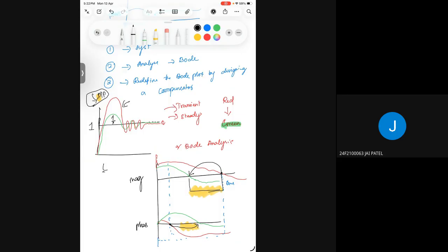That's why I'm using a Bode plot for both the systems. When I plot the Bode plot for both output signals, for my desired signal and also for whatever output the system gives me, I found that the green's gain margin and phase margin are far lesser than the red's. Then I understood that if I make my Bode plot of red nearly equal to the green, then my actual output will shift from red to green, right? So any one thing will happen if I make some control changes.